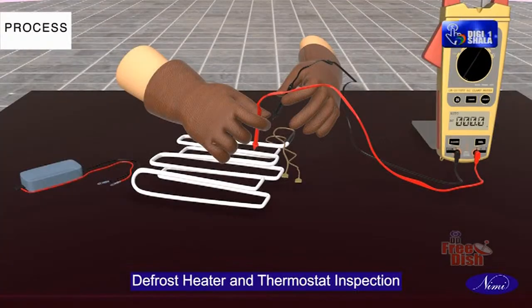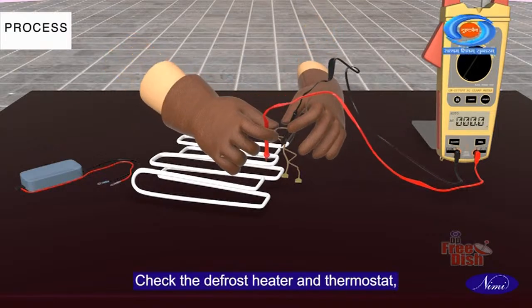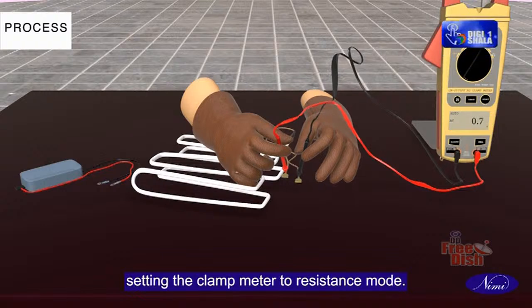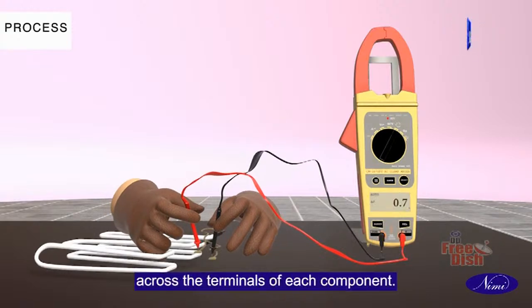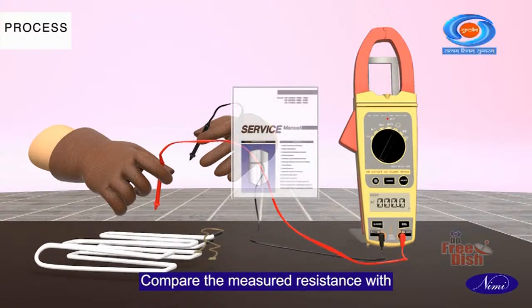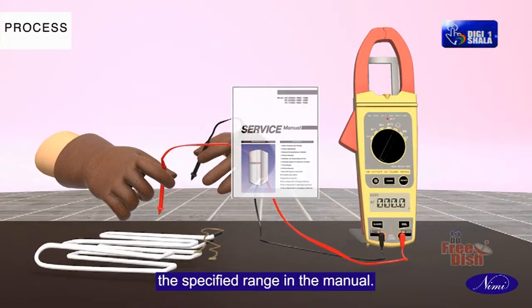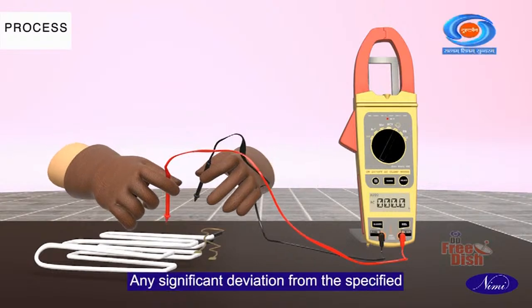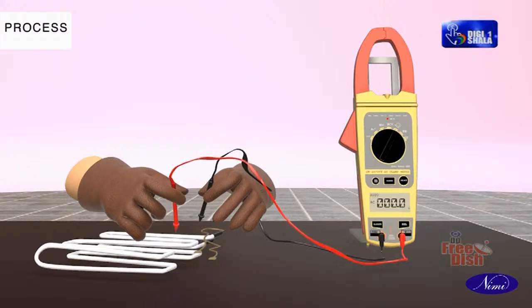Defrost heater and thermostat inspection. Check the defrost heater and thermostat, setting the clamp meter to resistance mode. Check the resistance across the terminals of each component. Compare the measured resistance with the specified range in the manual. Any significant deviation from the specified range might indicate a faulty part.